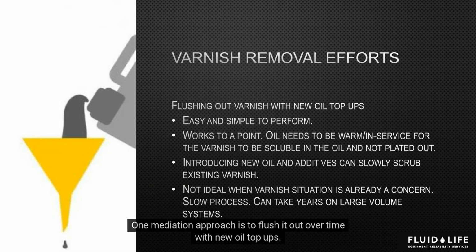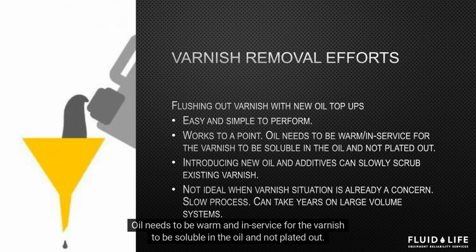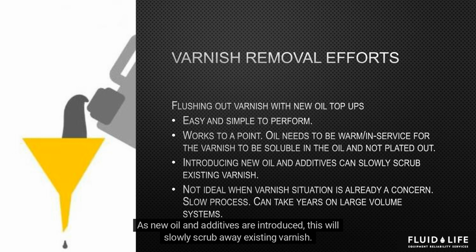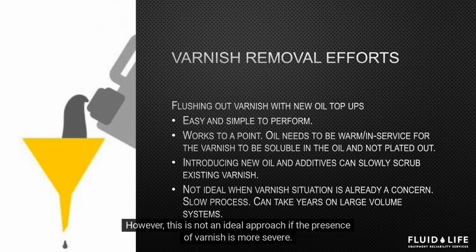One remediation approach is to flush it out over time with new oil top-ups. This is a relatively simple procedure, but only works to a point. Oil needs to be warm and in service for the varnish to be soluble in the oil and not plated out. As new oil and additives are introduced, this will slowly scrub away existing varnish. However, this is not an ideal approach if the presence of varnish is more severe. This can be a costly and slow process, which can take years on a large volume reservoir.